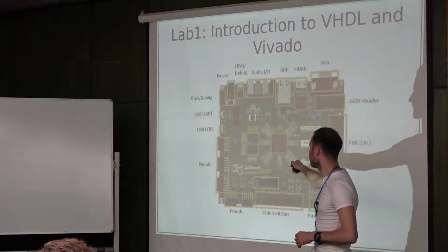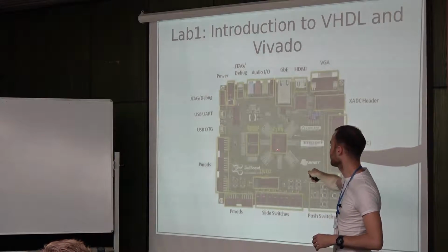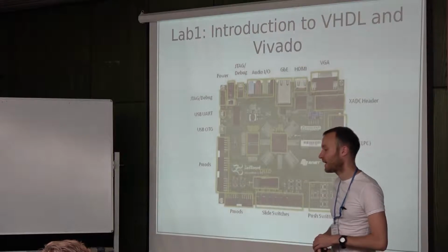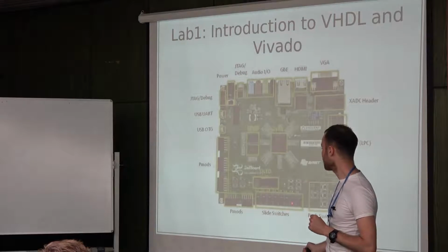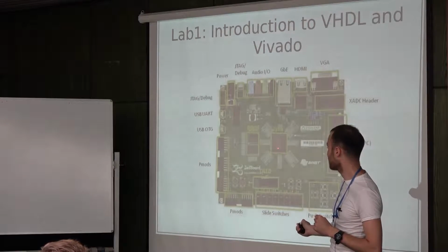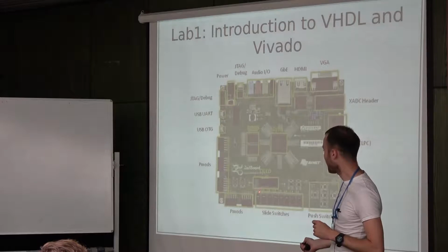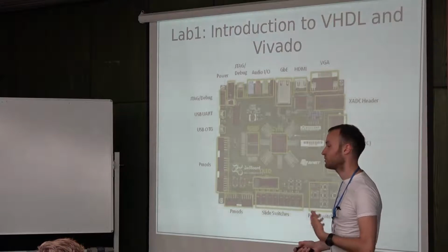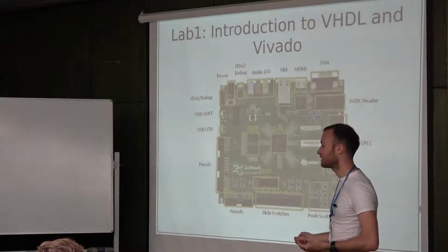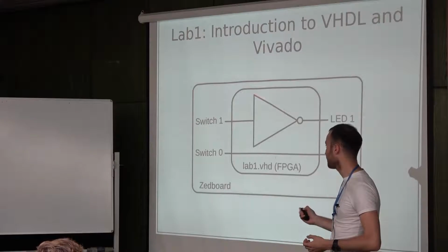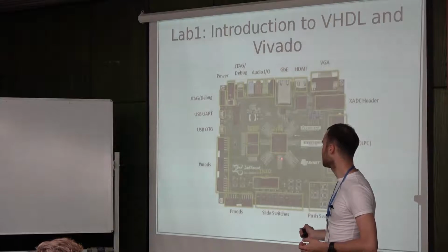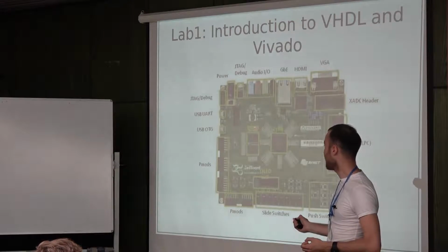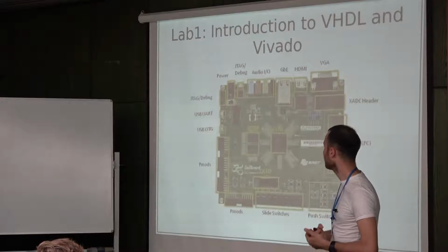Yeah, so this is the board that we'll be using. So the platform itself is here. This is a Zynq platform from Xilinx that has FPGA logic inside. In this lab, we will be using these slide switches that are routed to this chip, and we have a corresponding diode next to each slide switch. So the idea is to program FPGA and see if the behavior of the circuit is the one that we expect. In addition to Zynq platform, we also have DDR memory here, external RAM memory, but we will not need it.